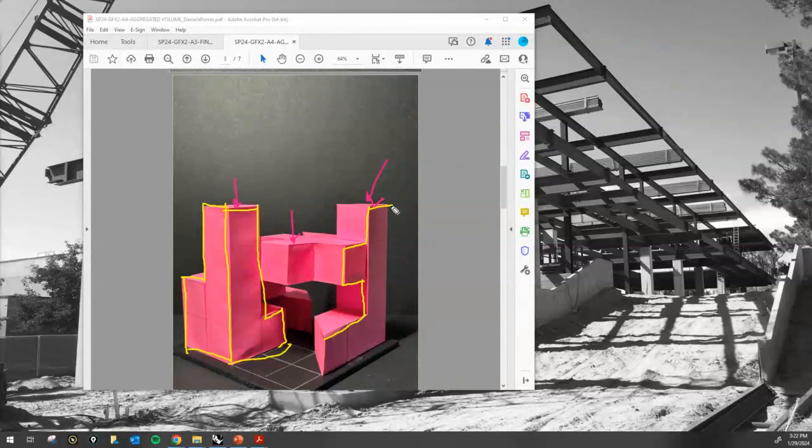All right, so those are the faces, the drawings that you were producing by hand, and we actually start taking this as a single component and do what's called an unfold, right? So maybe this piece is flattened right there. Maybe we bring this right here. We take that face and fold it, and we take this face over here and fold it over here. So in that sense, we create a template.